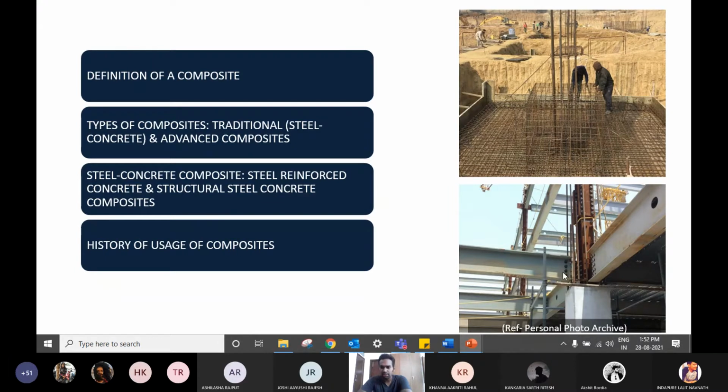So these steel beams are connected to the I section, which is inside the concrete column. And this column will be surrounded by concrete right after we do the formwork and pour concrete, so that everything is inside. That protects the steel from fire and also gives you an aesthetic finishing, right? It's a solid finishing on the outside.